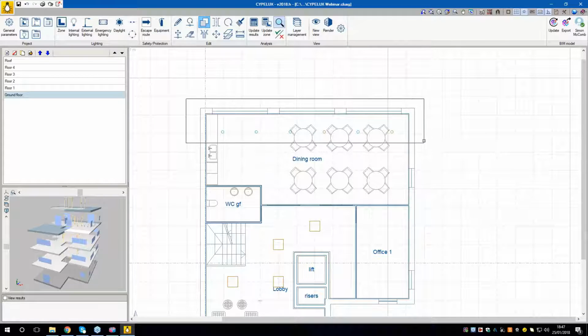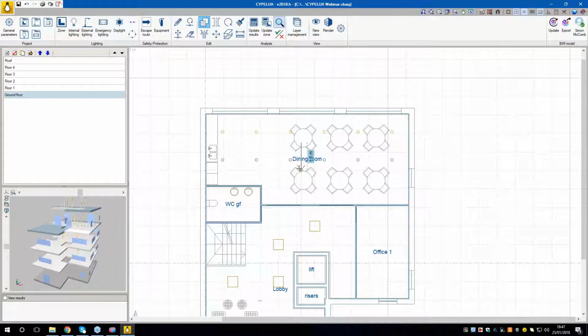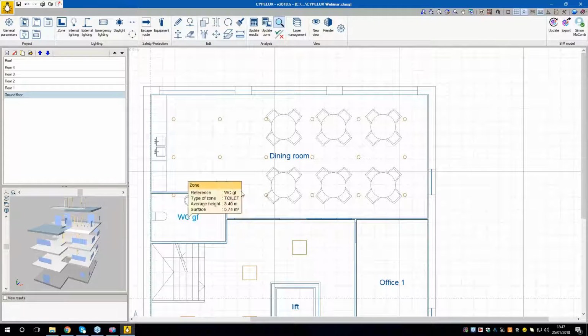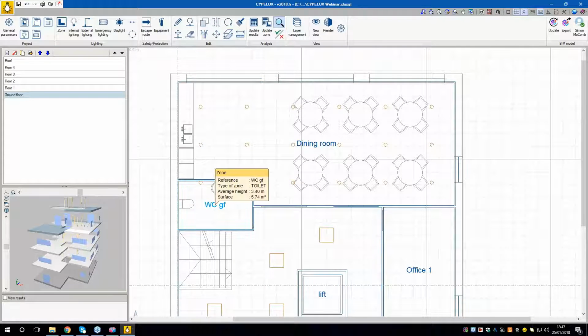We draw a box around the lights. We right click and then we left click, and we can drag the lights down to here. 1.5 meters away from these lights sounds reasonable. And again, another 1.5 meters. Okay, so you can see now the whole room's covered with these lights, and they're equally spread.